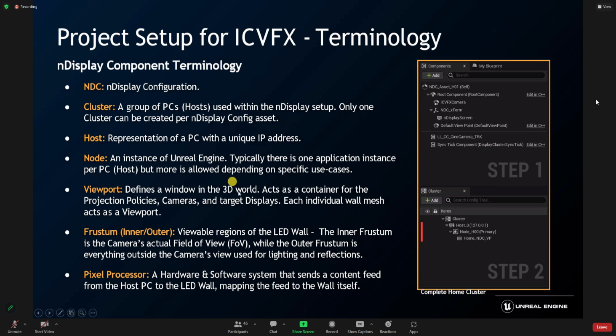A cluster, and this is a window that's part of the nDisplay config window editor. A cluster is a group of PCs or hosts used within the nDisplay setup. Only one cluster can be created per nDisplay config asset, but that cluster can have many different hosts.